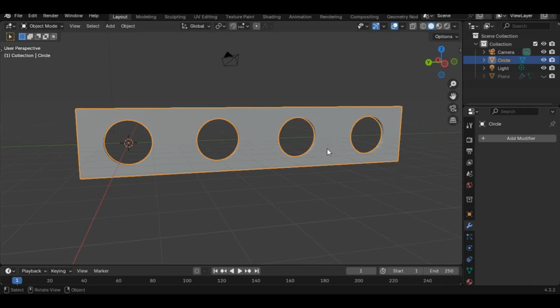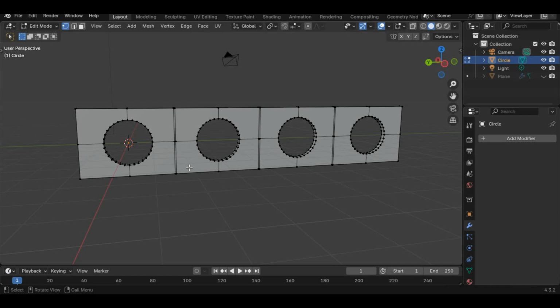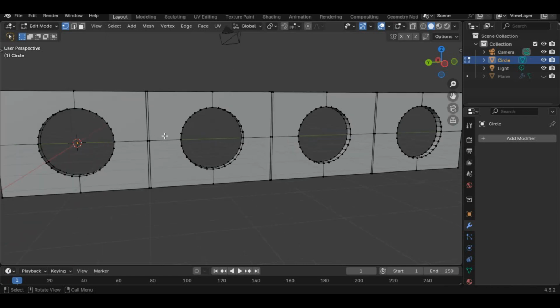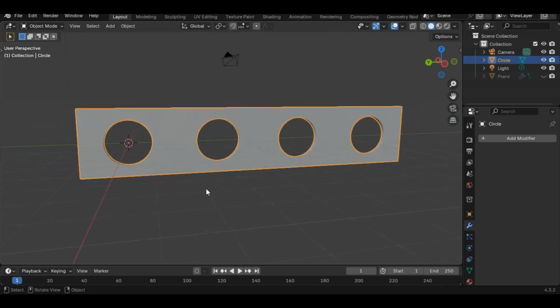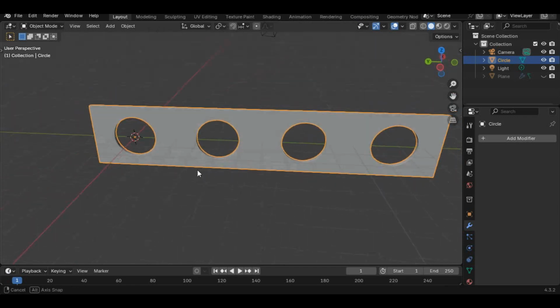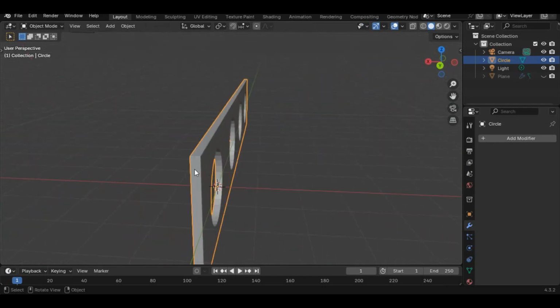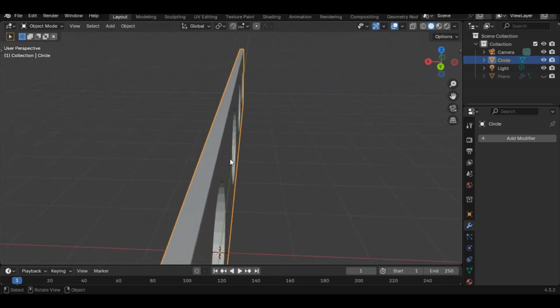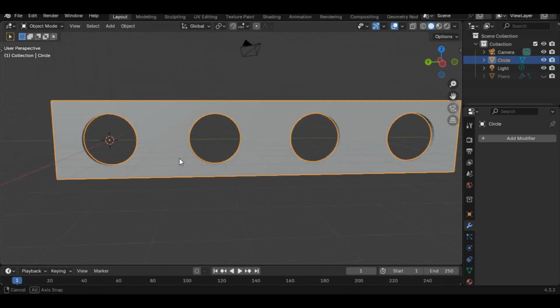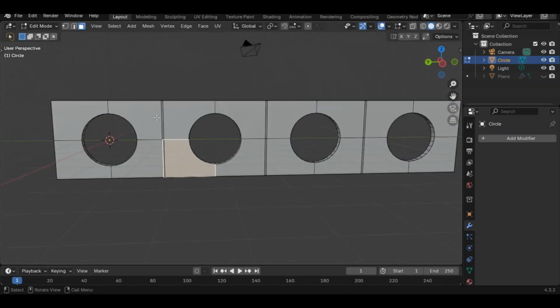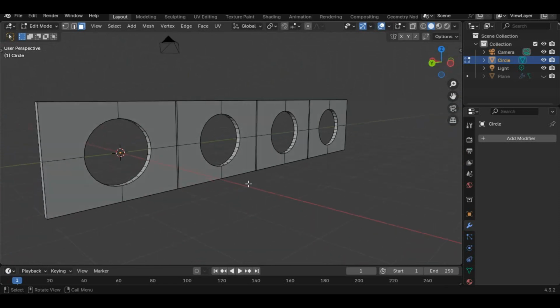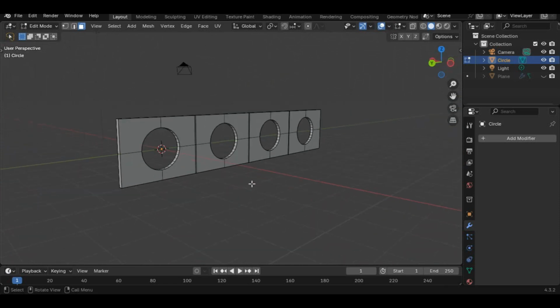So once you apply it and you go to your edit mode, you see that the lines have collapsed into each other, and you can see it's right here that these lines have collapsed into each other, and that's what makes the matching lines to be eliminated, and you still have your bevel here, you see. So it's looking good, but I'm not really very comfortable with this in edit mode. So a better method is the other easier method.